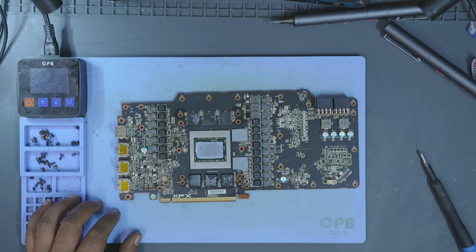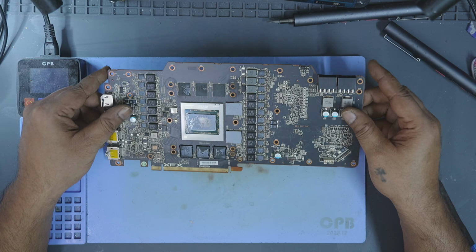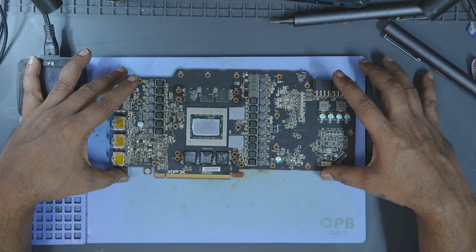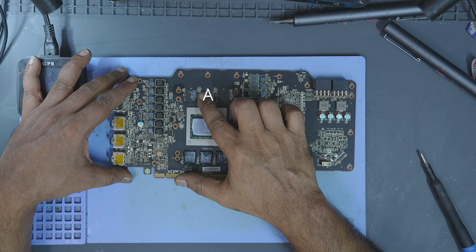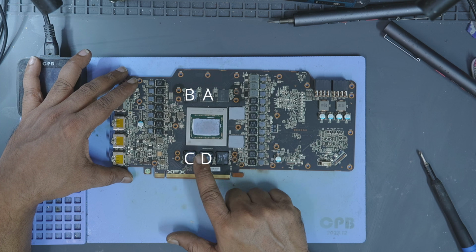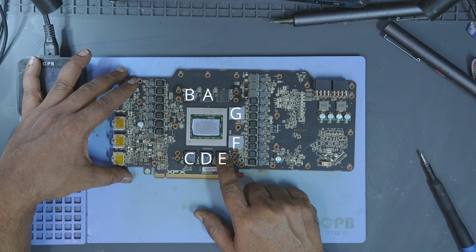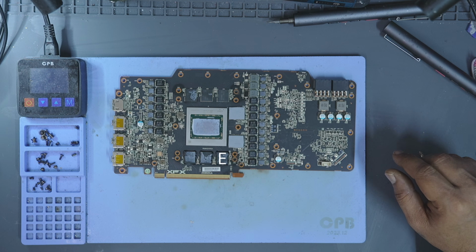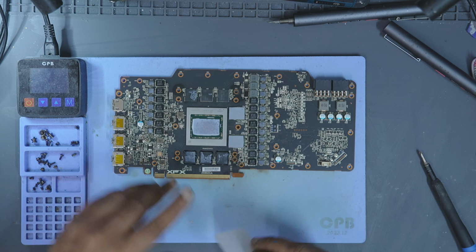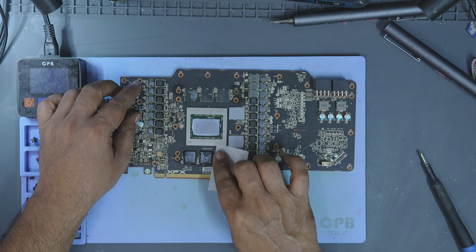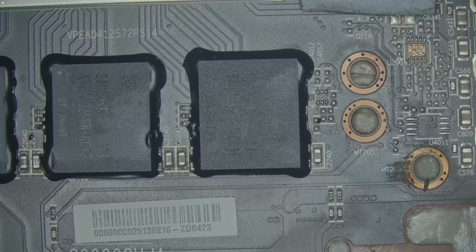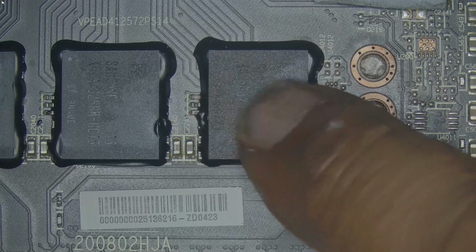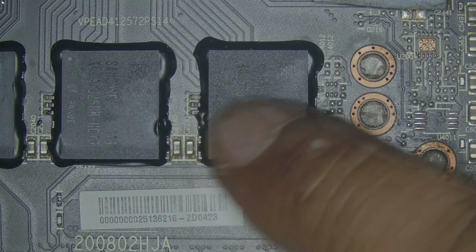On AMD's RX 6800, 6800 XT, 6900 XT, and 6950 XT, the memory channel layout goes in sequence: A, B, C, D, E, F, G, and H. Since the fault is on channel E, this is the chip we'll be working on. Let's take a closer look under the microscope. Here, you can clearly see the epoxy surrounding the E-channel memory chip.